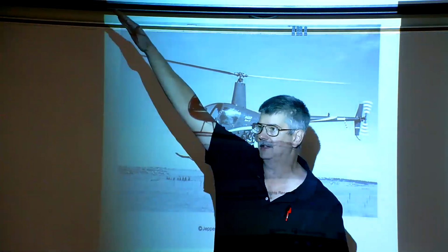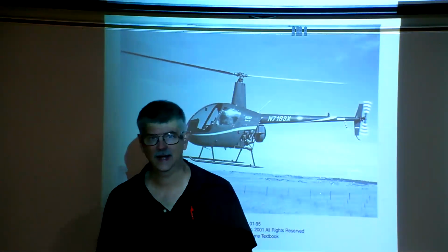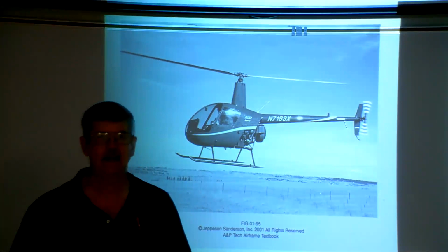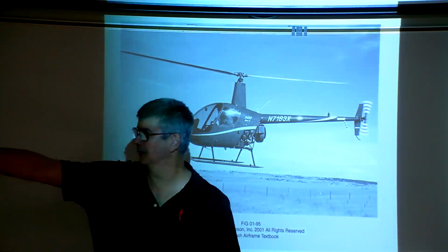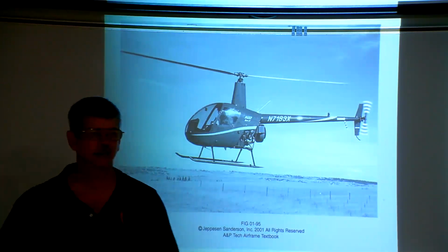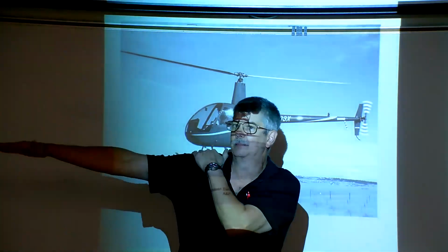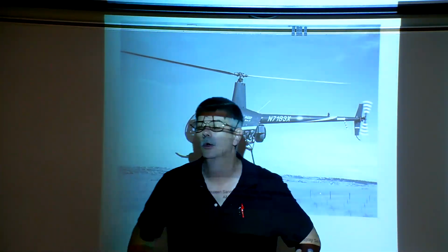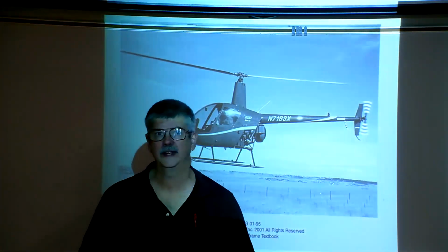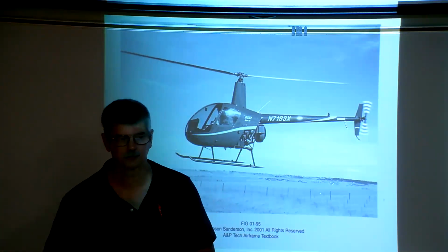So we have these blades that have all these forces trying to make them go up and down, lead and lag, and then we also need to pitch the blades, okay? So the rigid rotor, when they first were built, was so rigid that it could only pitch. All those forces would fatigue the rotor blades, and there were a lot of rotor blade failures.